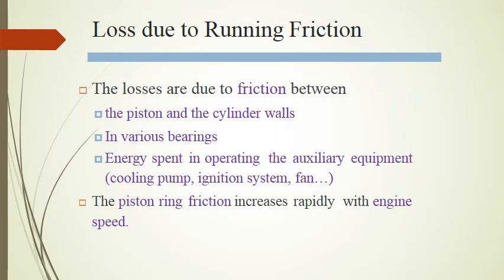beyond top dead center, the burned gases are swept out better by the fresh charge, and the energy spent in sweeping out the clearance volume results in increased volumetric efficiency. Consequently, the exhaust valve is often set to close a few degrees after top dead center on the exhaust stroke. It should be noted that it is quite possible for both the intake and exhaust valves to remain open or partially open at the same time. This is termed as valve overlap. The overlap, of course, must not be excessive enough to allow the burnt gases to be sucked into the intake manifold or the fresh charge to escape through the exhaust.